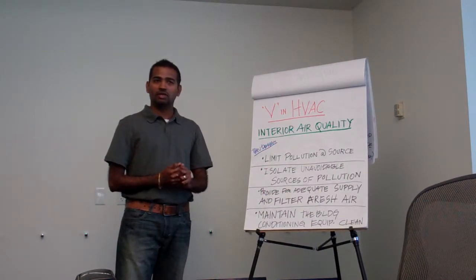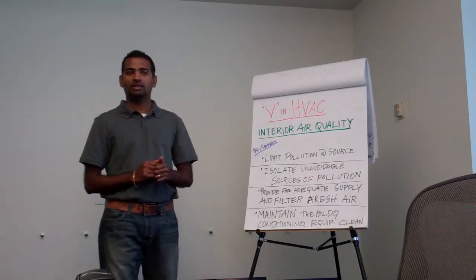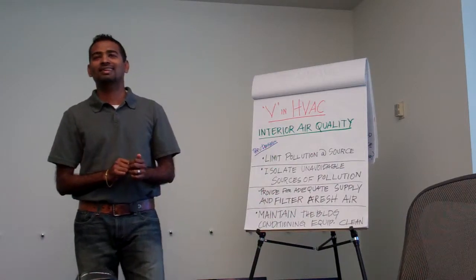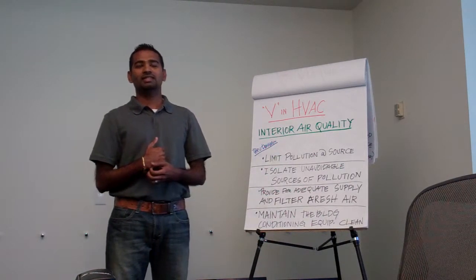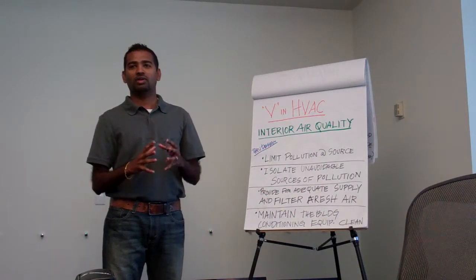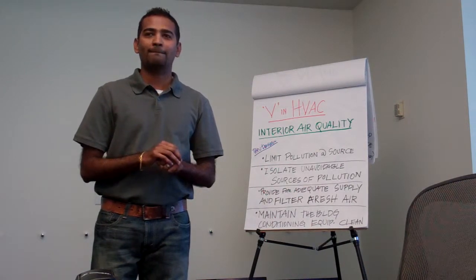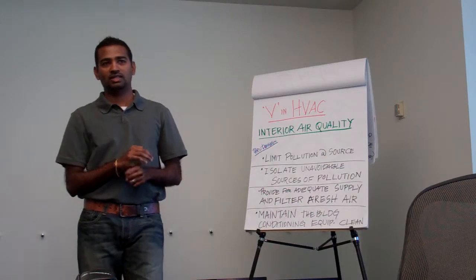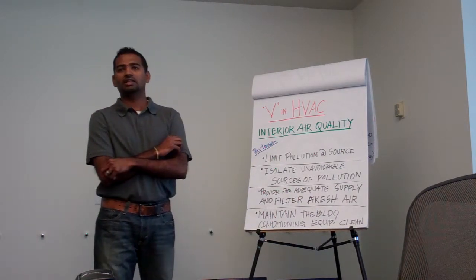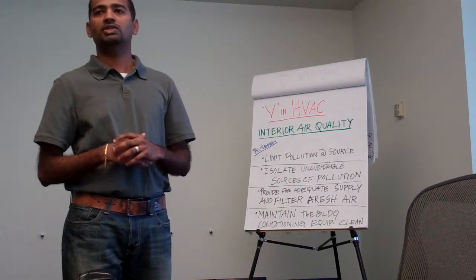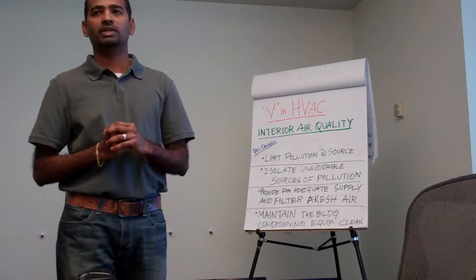Do you guys agree or disagree? Agree. And why do you agree? As an engineer, why is interior air quality very important to energy conservation? Accounts for about 20 to 30% of your load. Correct, which is through ventilation. That's our primary way of solving interior air quality issues. At the peak condition.